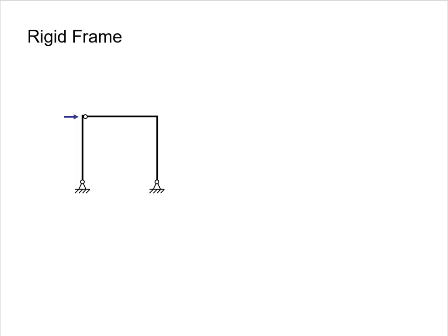Consider this simple example. Remember that in an elevation view, pin connections are shown as hollow circles and rigid connections are shown as connected lines. As the top of the level moves with the loading, the left column is pinned at the connection and support, so it experiences rigid body motion. That is movement without changing shape. But the right column is rigidly attached to the beam. For that connection to move to the right, it needs to rotate, thus causing bending in both the beam and the column.